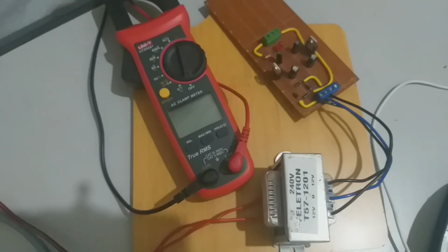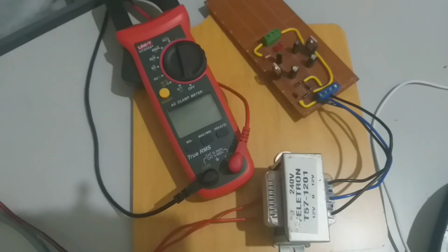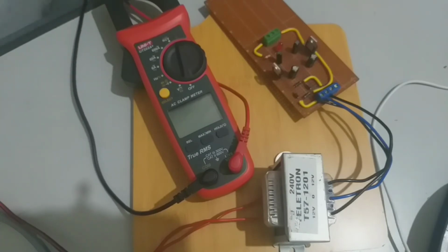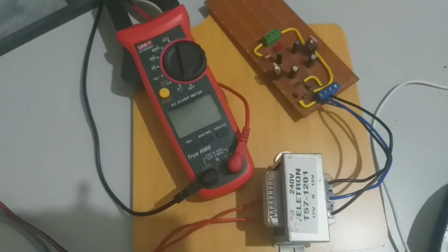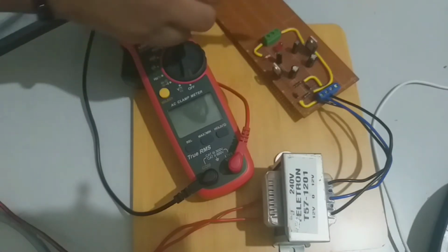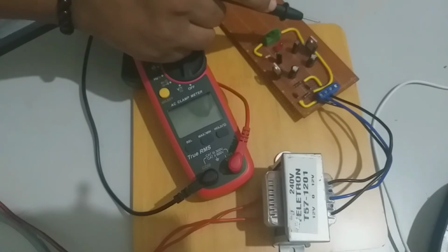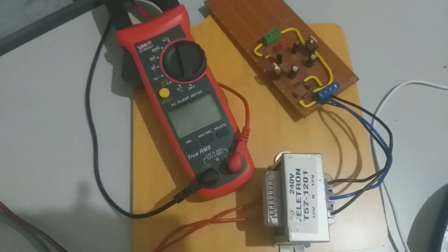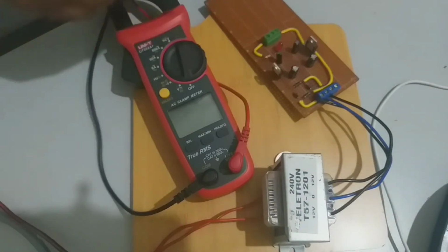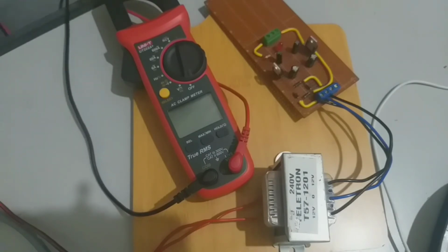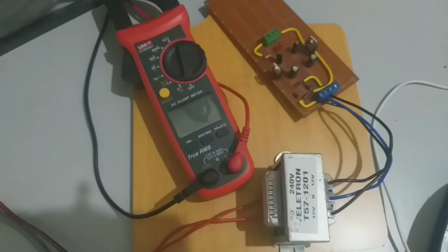Next, the fourth process involved in the circuit is regulation. A regulator provides a constant output voltage for a varied input voltage. In this circuit, we use two voltage regulators, the LM7805 and the LM7905. The LM7805 voltage regulator provides a positive voltage output, and the range of the output is within positive 4.75 volt to 5.25 volt.